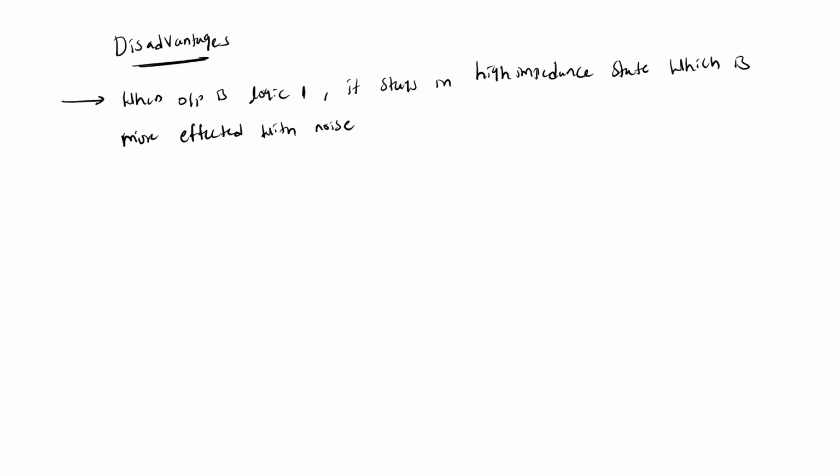logic high. Okay, and it requires precharging. And there are cascading issues also. If you cascade this dynamic CMOS logic, there are cascading issues that I will explain to you. There is also some race problem.